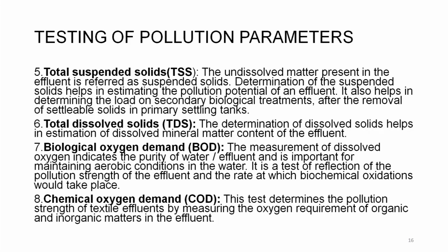Then comes the testing of total suspended solids, TSS. The undissolved matter present in the effluent is referred to as suspended solids. Determination of the suspended solids helps in estimating the pollution potential of the effluent.